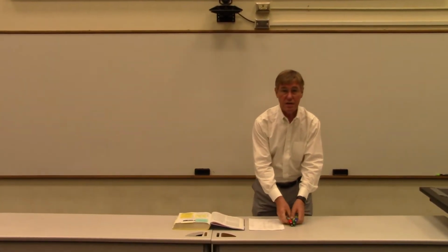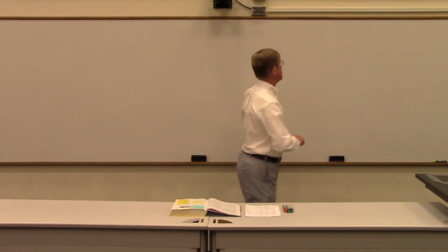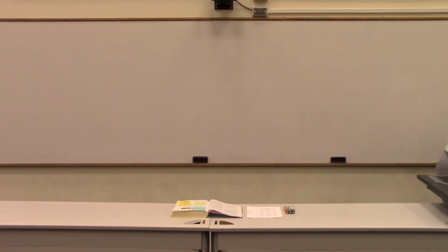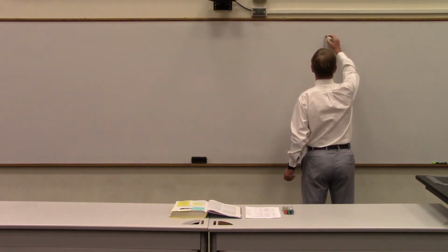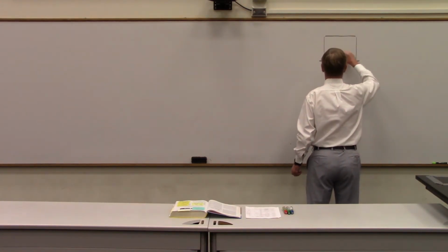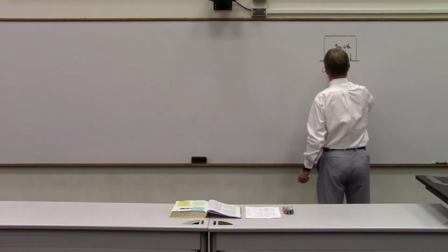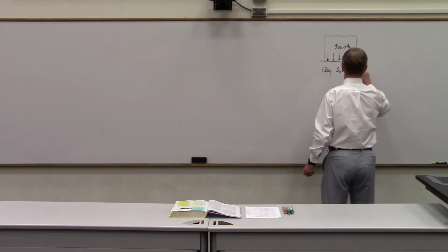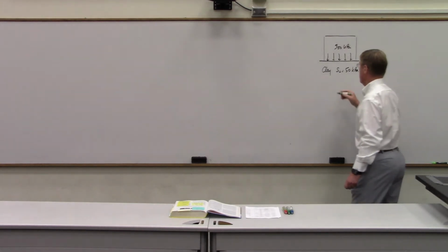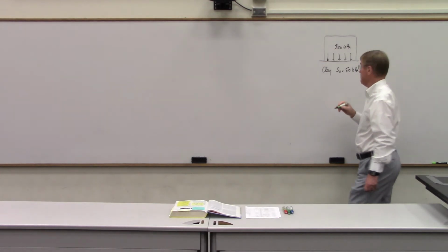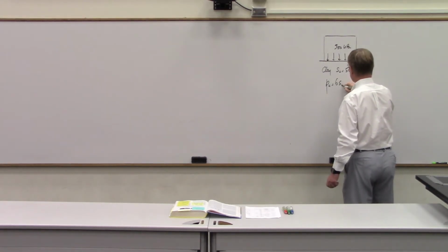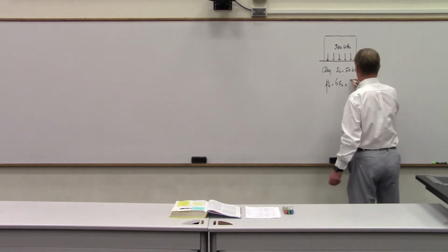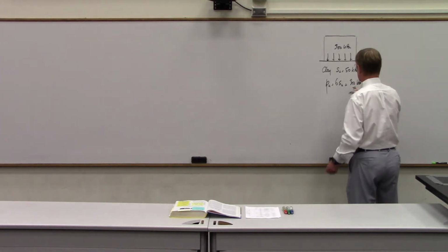So I wanted to do some calculations. You remember I said that the pressure under the silo was 300 kilopascal. And the soil was a clay that had an undrained shear strength equal to 50 kilopascal. And if you remember what we discussed with the Tower of Pisa, we said that the ultimate pressure that you can place on a clay, on a fine-grained soil, can be estimated by 6 times the undrained shear strength. So in this case, it would be 6 times 50 or 300 kilopascal. Okay, so the ultimate pressure is 300 kilopascal.